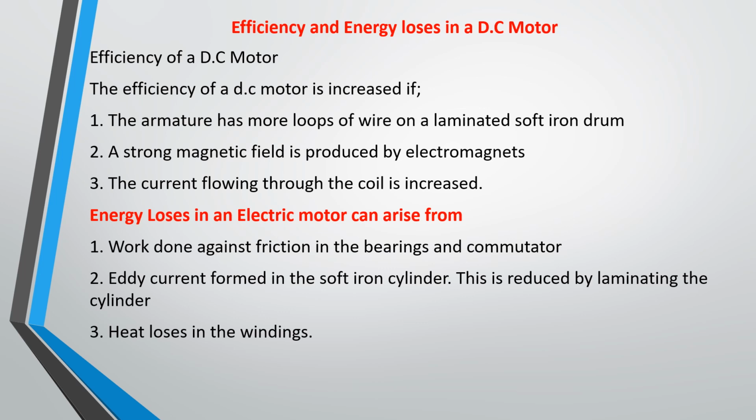Eddy currents are induced currents that oppose motion in a magnetic field. So the eddy current formed in the soft iron cylinder can actually make the electric motor lose energy, and this is reduced by laminating the cylinder.